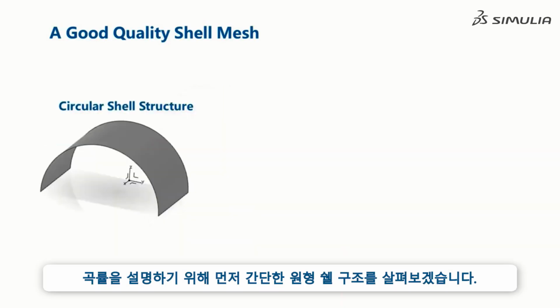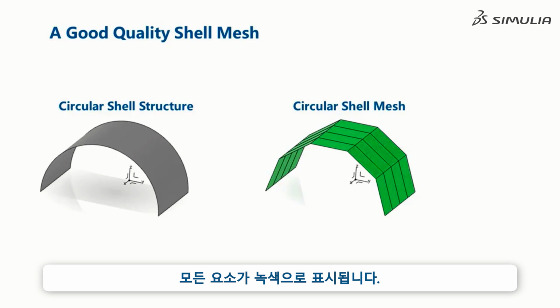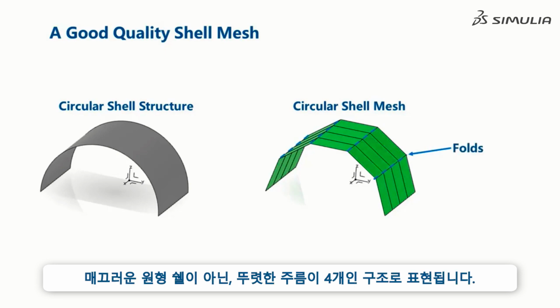To explain this, we will examine a simple circular shell structure. If we mesh this surface, and check the mesh quality, all of the elements appear as green. However, we have not adequately refined the mesh along the circumferential direction. If we run a simulation using this mesh, the structure will act like a structure with 4 distinct folds, rather than a smooth circular shell.